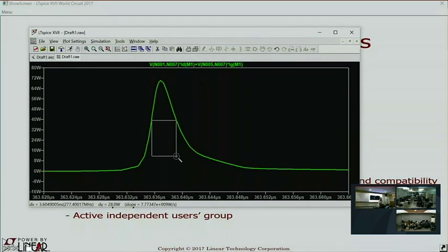So if I position the size of the box, pretending I'm going to zoom in, this dx, the distance from there to there, is read out down there as 3.7 nanoseconds. Well, that might be okay. I mean, yeah, it's 70 watts, but 4 nanoseconds. Maybe the transistor doesn't know it's dead yet, right?